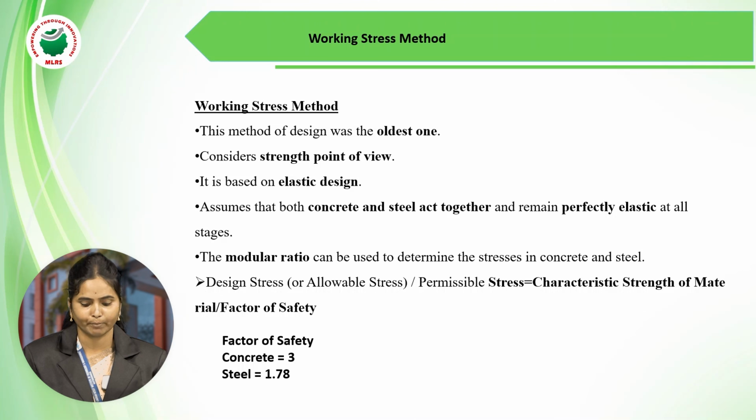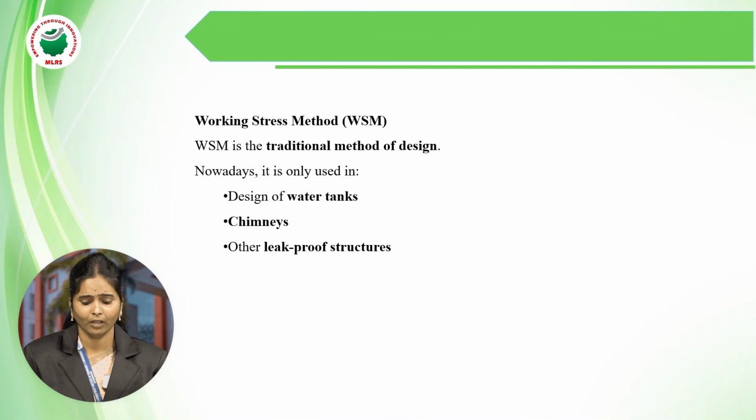In this working stress method, we have to take the value of factor of safety for concrete as 3 and steel as 1.78. Working stress method, WSM, is the traditional method of design. Nowadays, it is only used in the design of water tanks, chimneys, and other leak-proof structures.